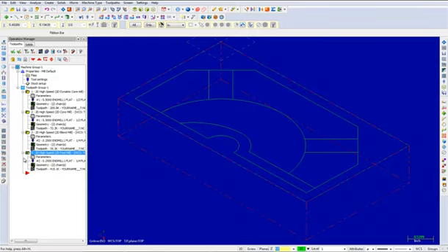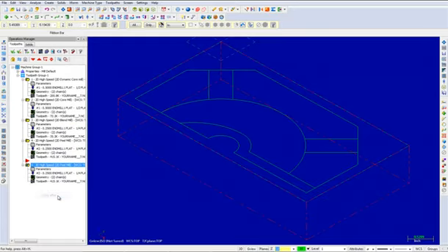Right-click and hold the right mouse button down and drag the operation to a point below it. Release the right mouse button and select the option Copy After. Make sure that the insert arrow is below the last toolpath. Otherwise, pick the icon to move the insert arrow as shown.